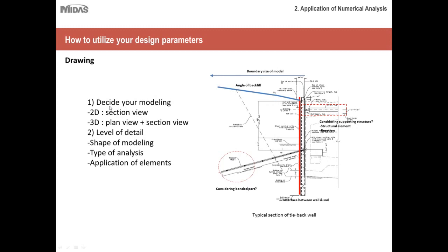And then another key thing that you need to take into account is whether or not you want to do a 2D section view or a 3D plan view plus a section view. Now there are certain advantages and disadvantages of each, but essentially simpler, smaller scale projects with simple geometry would best be done with 2D analysis, whereas larger scale projects with more complex geometry would best be done in 3D. And we'll go more into detail into this later on.